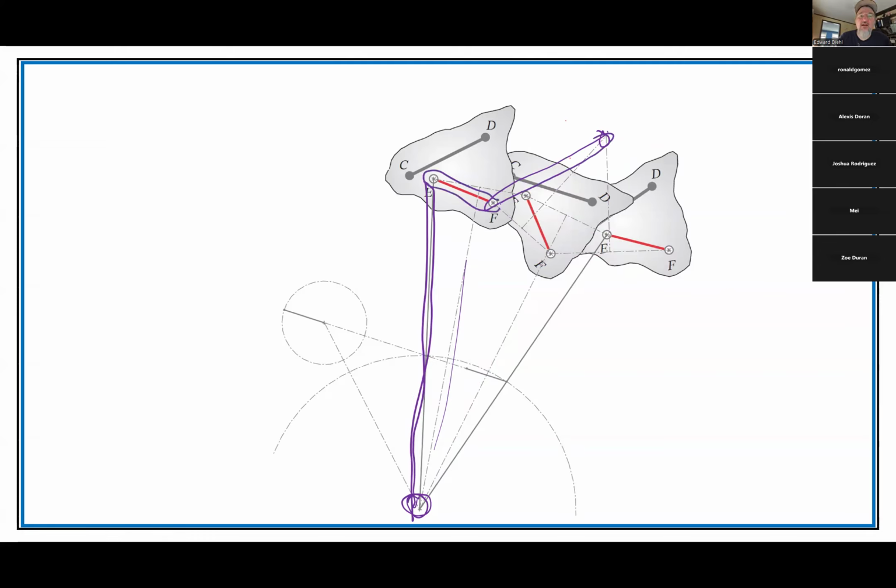So now we've made ourselves a four bar. That's the four bar that we've just made. And of course we could attach a driving dyad onto it. So there's the driving dyad and the extended. There's the crank and there's the coupler of the driving dyad. A partial segment of the rocker slash crank of the primary four bar is now the rocker for the driving dyad. And then of course this is the ground right there.